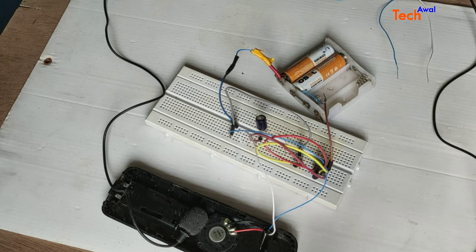it is taking time to charge the capacitor. Discharge is quicker, okay, because it is discharging through a 10 kilo ohm resistance. But charging is through 330 kilo ohm, and since it is a 10 microfarad capacitor, it is noticeable that it is taking time.